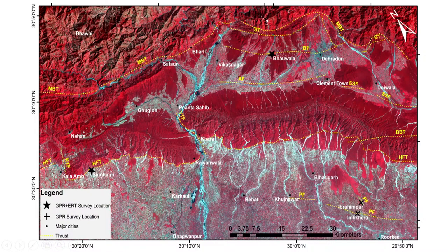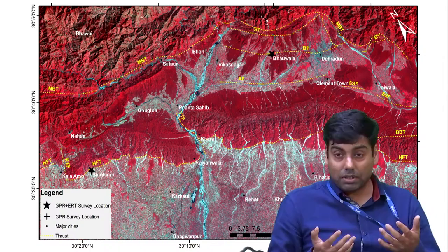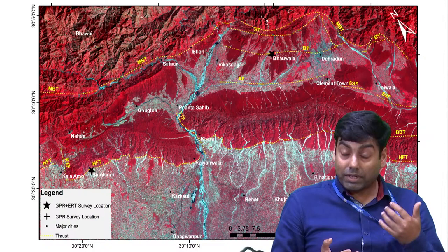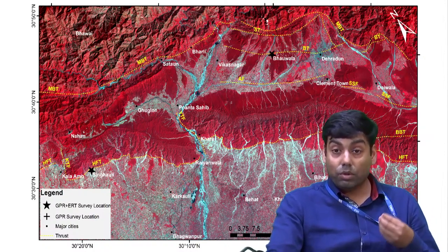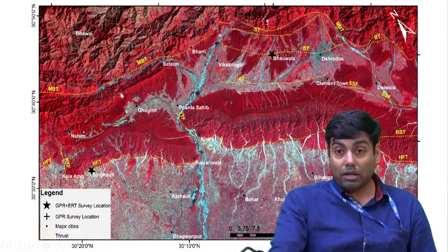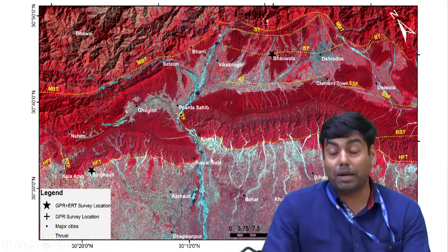And these are the active faults in the Dehradun region. When you are going to do this active fault mapping, you know there are some criteria for active fault study, like sudden elevation change, lithology change, scarp development. If you are getting such information in any region, it means there could be a fault. And once you get this surface feature, surface change, or anomaly, then you go for trenching, and then you can confirm the fault, you can date the fault, and then you can give the information about the paleoseismology.